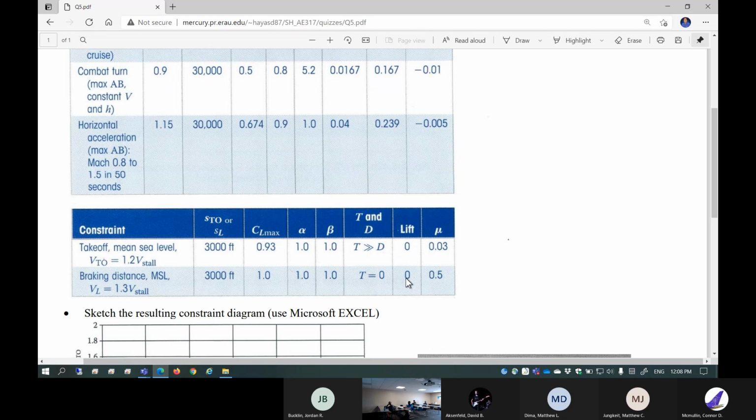And then I said, well, why don't you plug in CD0 information into the takeoff constraint and see how much impact you have? And then he reported back to me, there's not much impact. So CD0 equal to 0 is about the same result unless you have an airplane with CD0 equal to, what, 1. CD0 equal to 1 means probably your airplane is like a flat plate perpendicular to the direction of the flow.